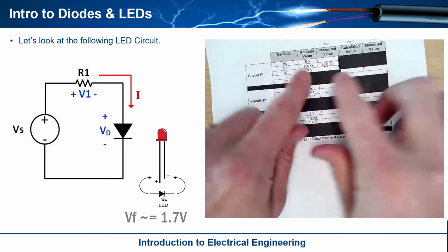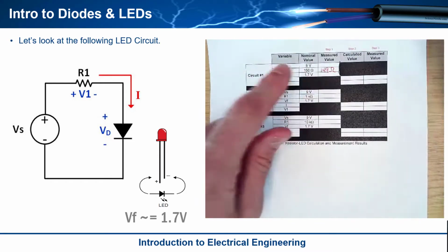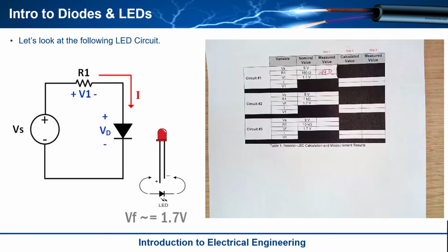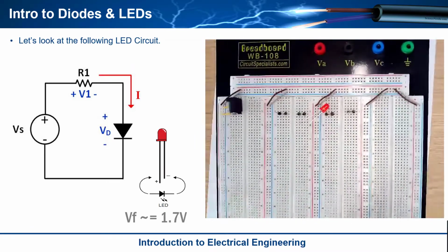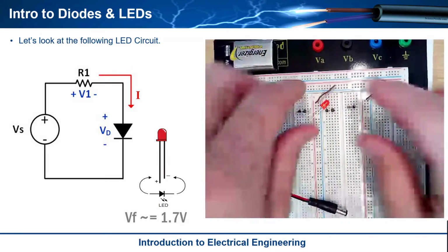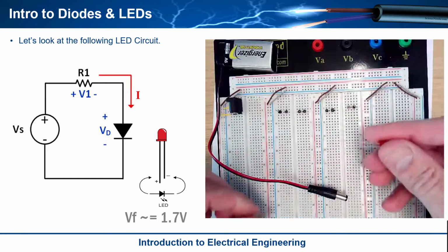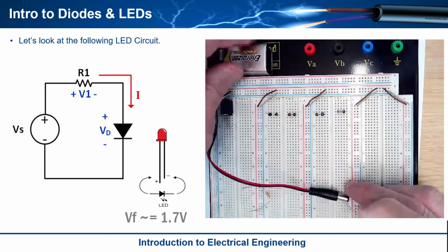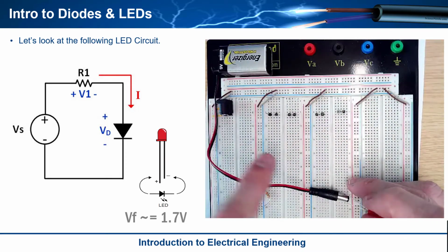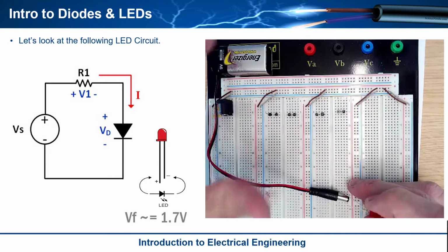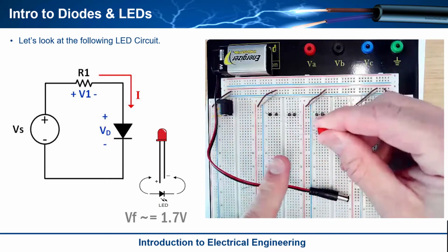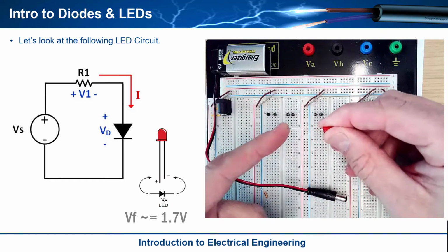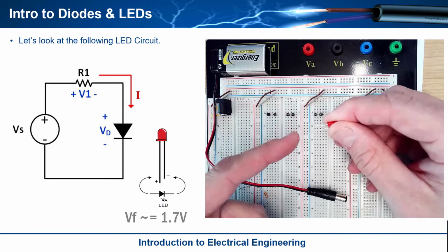Okay. Now we're going to measure the 9-volt battery and the forward voltage, but we have to actually do it with the circuit powered, because remember, once you start pulling current out of a battery, it isn't exactly 9 volts. So let's come along, and here's our breadboard now, and here's our battery, and now let's build up the circuit. It turns out it's pretty easy when you build a series circuit with an LED, because I have my power supplies routed throughout the breadboard, so all my red rails are 9 and all my blue are connected to the negative terminal, or what we call ground. This particular LED has a longer lead indicating the anode, so that's how I know that the anode is this one and the cathode is this one.